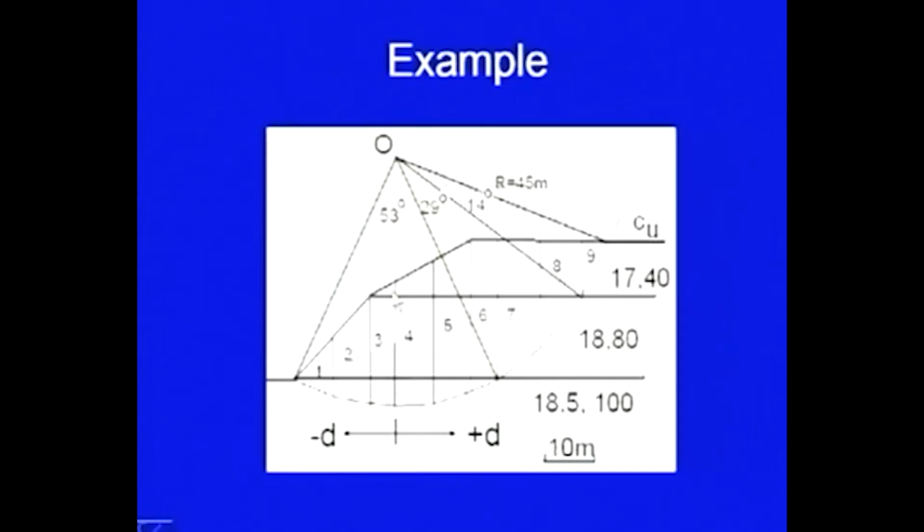When we go to slice number 3, here this smaller area you have to find out. So, this smaller area into 17 plus this area into 18 plus this area into 18.5. That is the way you will be calculating the weights. Also, you can find out the CGs. You can find out the CG of all these figures. I am taking those CGs at the mid of the slice. It is not going to make much difference.